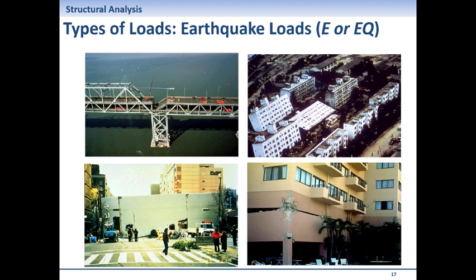So when the earthquake happens and it's moving the sand and the ground, at some point the sand may behave like just water. All because it's a porous material, yes? So if all these little voids are connected inside the sand, then it becomes basically water.